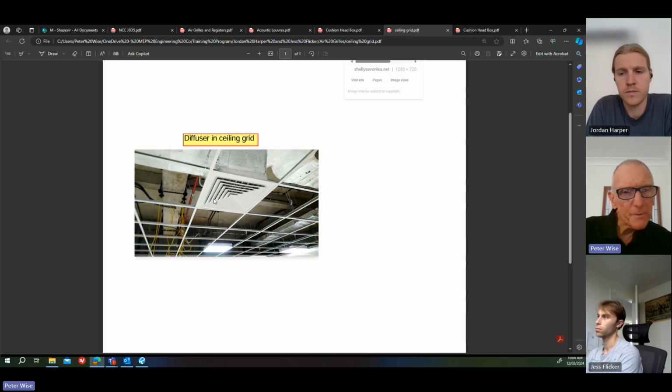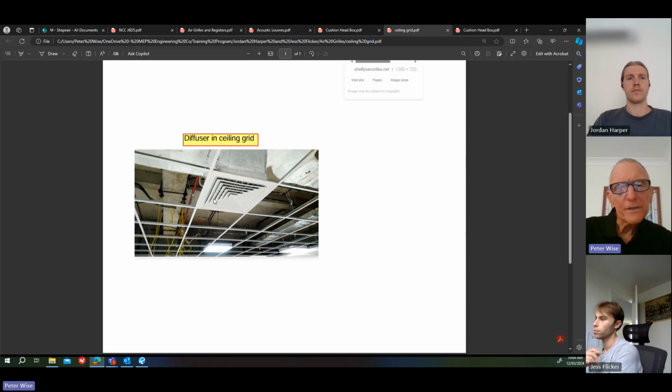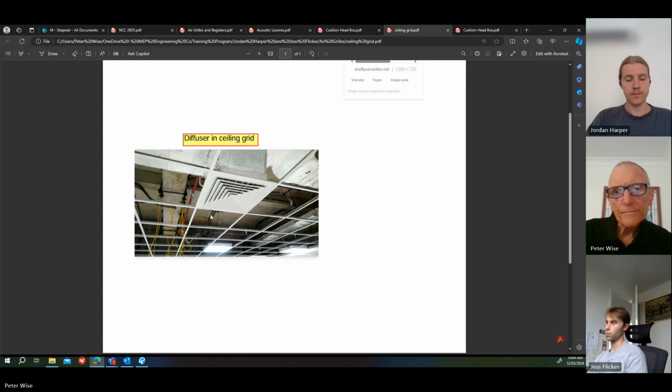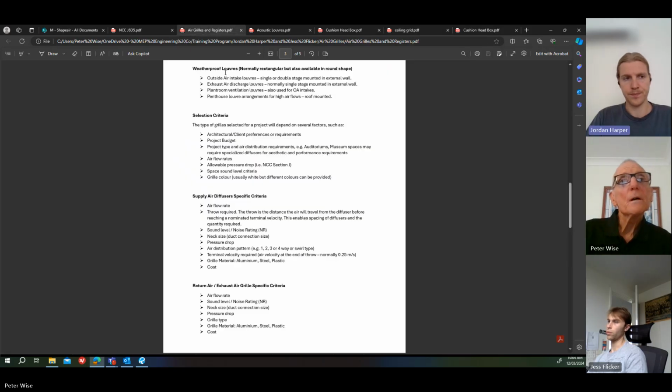Okay, I'm getting off the track here a bit, but I'm just saying things as they come to mind, because these are the practical things to consider. So quite often when you get to a certain point, and you just have to judge it on the project, with the return air grill, you might have to have a solid connection because it's too much air to convey with flexible duct. I hope that makes sense. Yeah. Yeah.